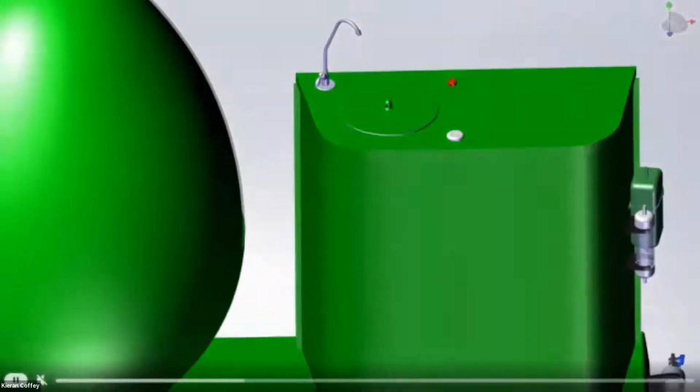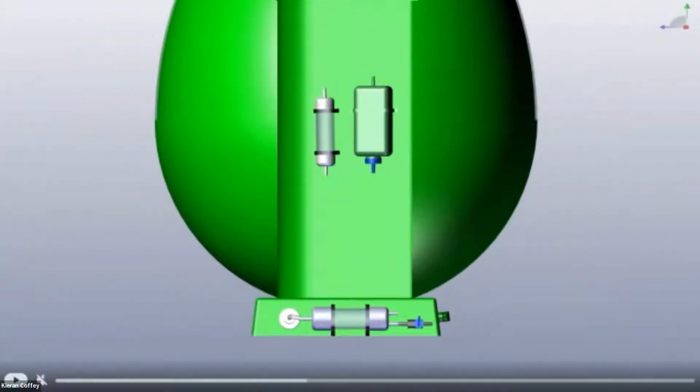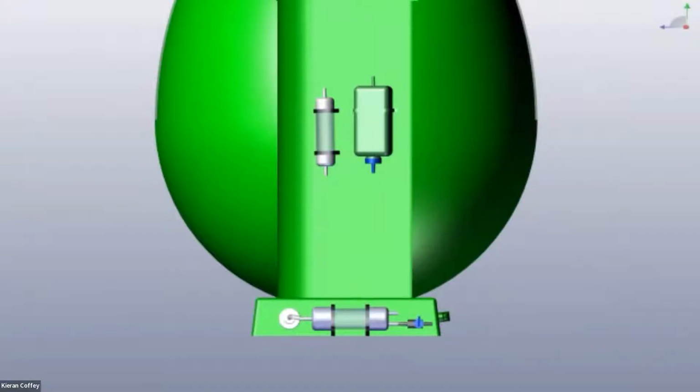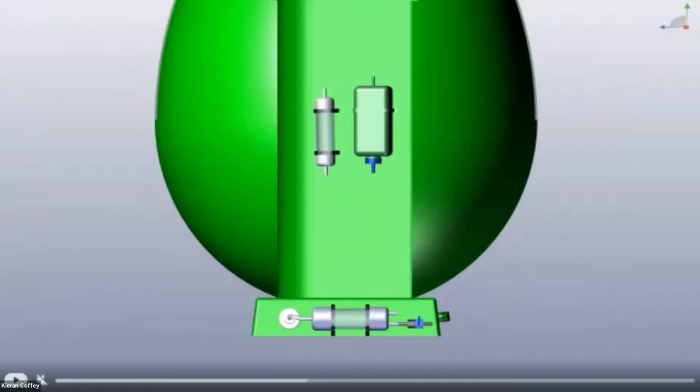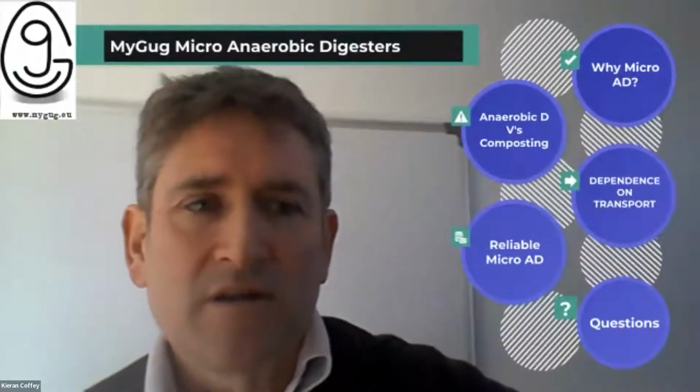Okay, and just a question on that. Do you need to do any level of cleaning of the gas to remove any H2S or CO2 in advance of its use? Again, on this video, it shows there's a filter here. So you can see the green filter, the gas flows through that filter, and we use activated carbon, so that will remove the H2S from your system. That's the only filtering that needs to be done.